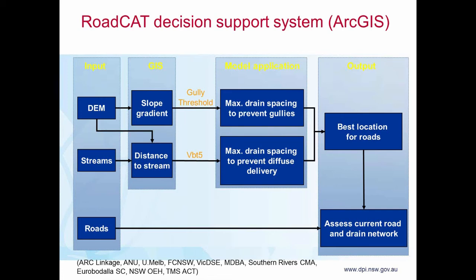You can look it up. It applies all of these concepts that I've talked about for road drainage in the landscape in a GIS platform, to work out the best location for your roads and also the drains. The inputs to it are obviously a high resolution DEM. The higher the resolution, the better. If it's LiDAR, that's great. If not, use the best you've got.